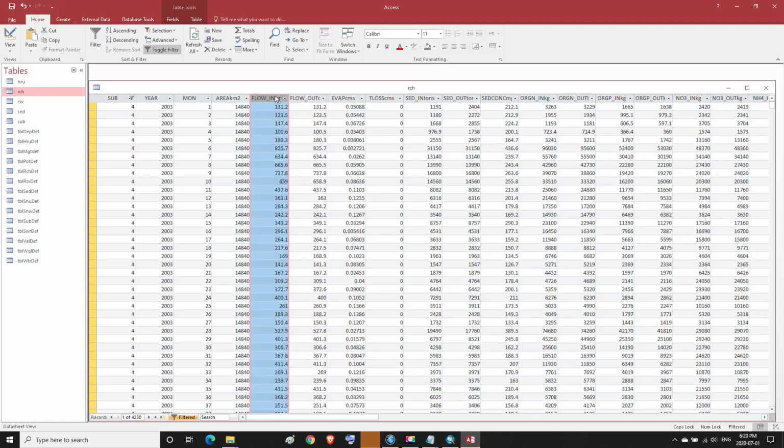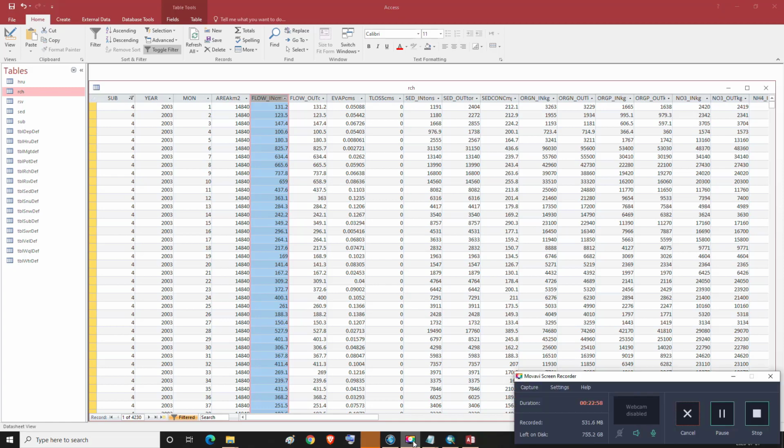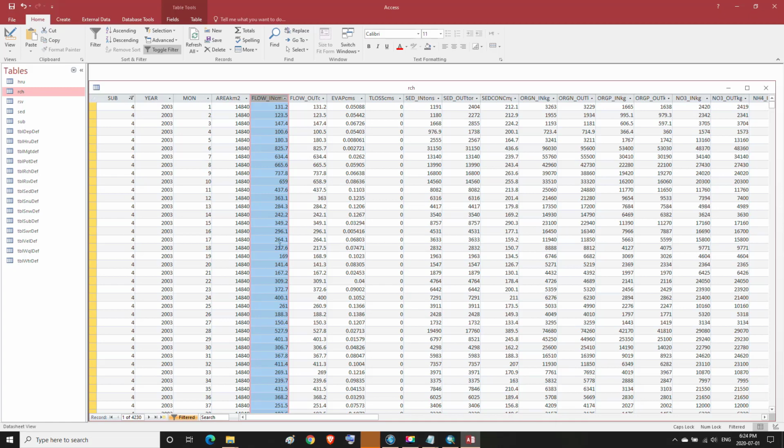We compare these daily discharges, or flow-in at Dokan Dam site, resulting from the simulation in ArcSWAT after performing the calibration, after converting them to monthly discharges, with the values of monthly observed discharge data to show the extent of the model's conformity to reality.